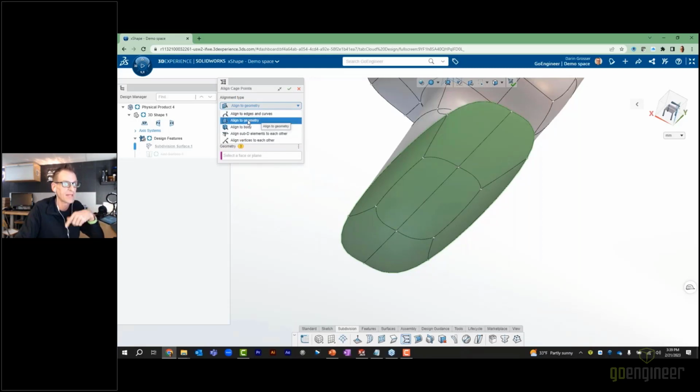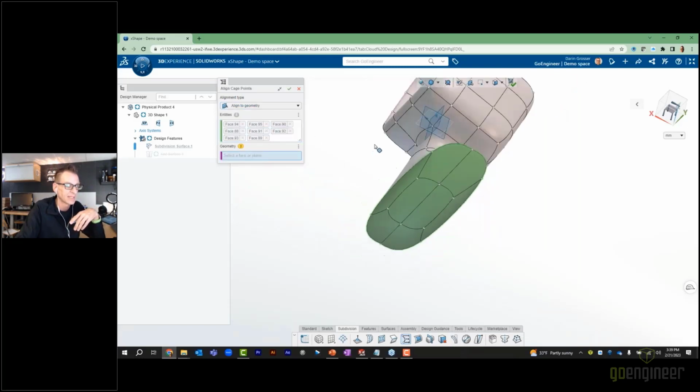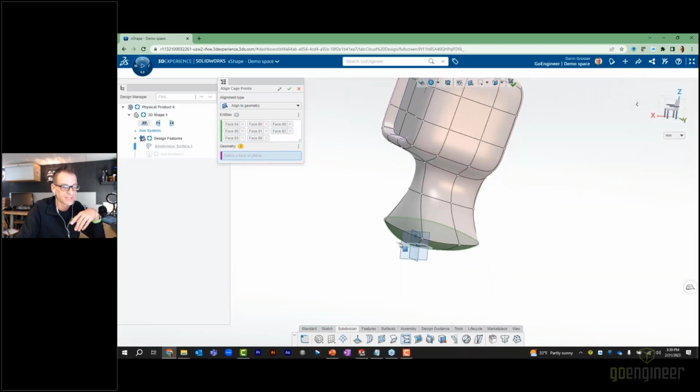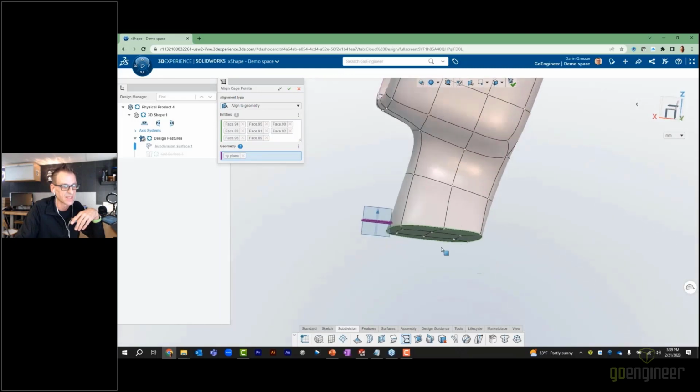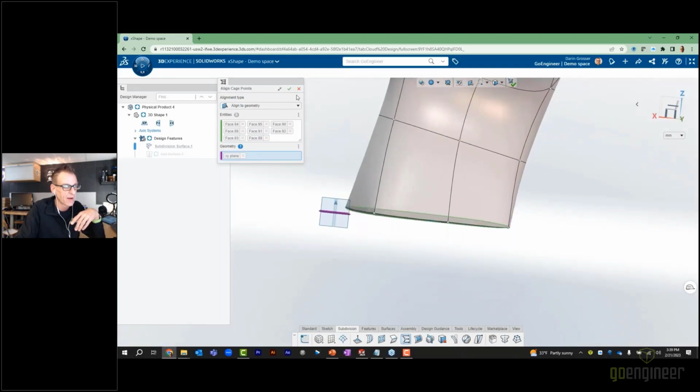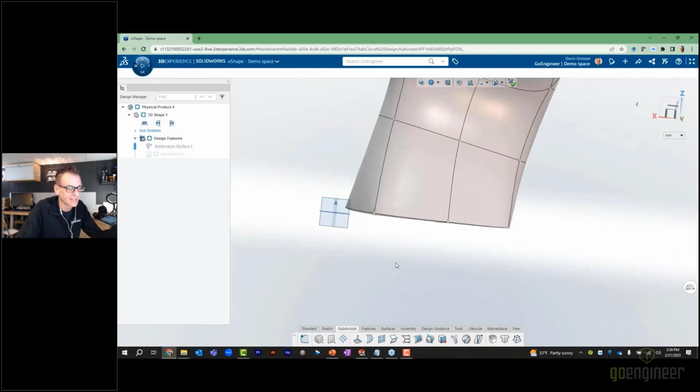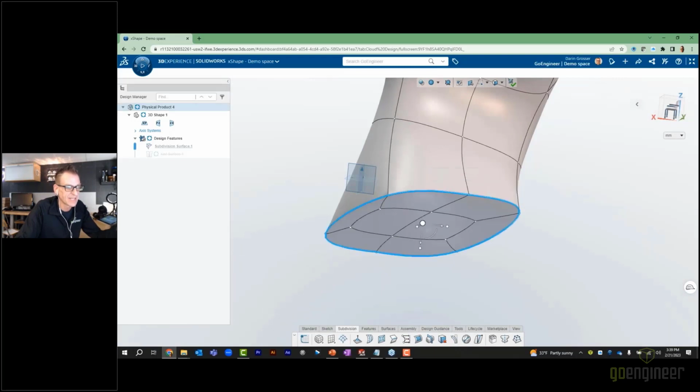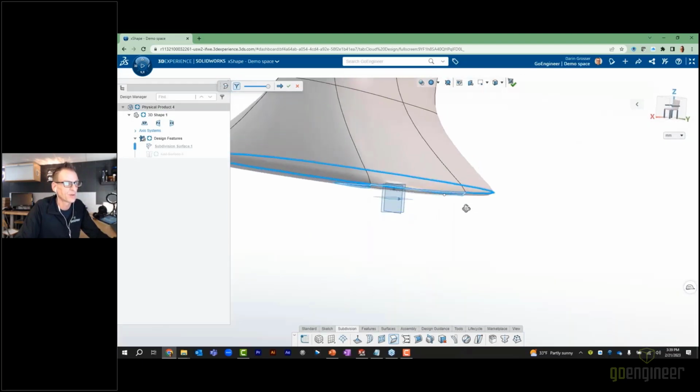But you can align that to some existing geometry, to imported geometry from SOLIDWORKS, had I pulled that stuff in, or in this case, really to any geometry like a plane. Now in my case, if I align that to this top plane, you'll see that flat face will go perfectly smooth and everything selected will be absolutely linear there. Now at this point, if I like that linear, but then I wanted to take this outside edge and maybe deal with just a little bit of a smooth crease on that, we can do that. And that's going to look really, really nice.